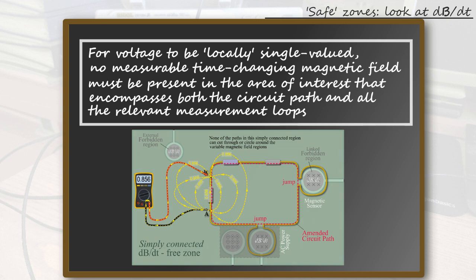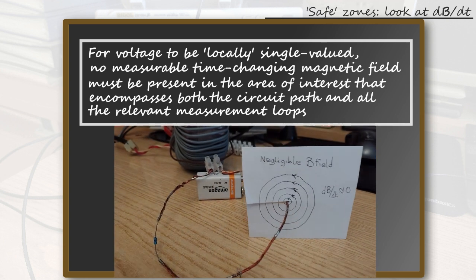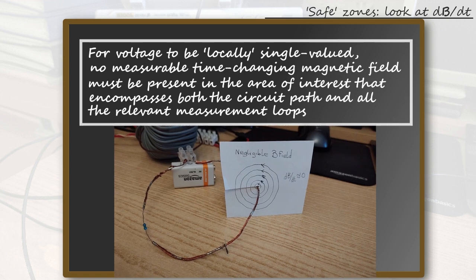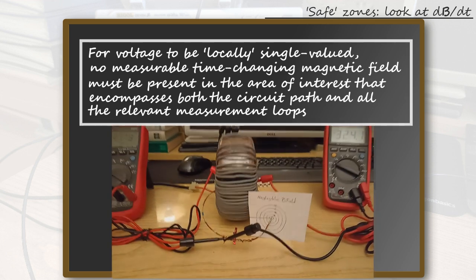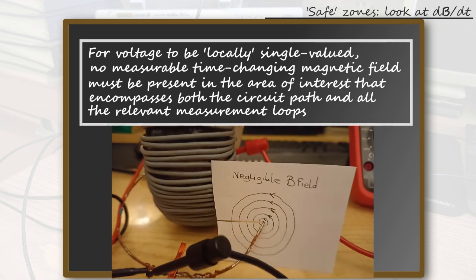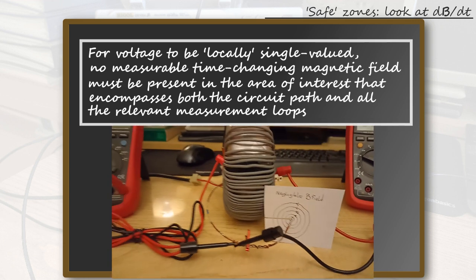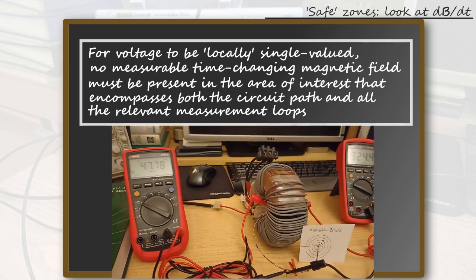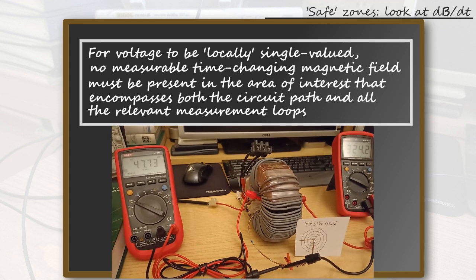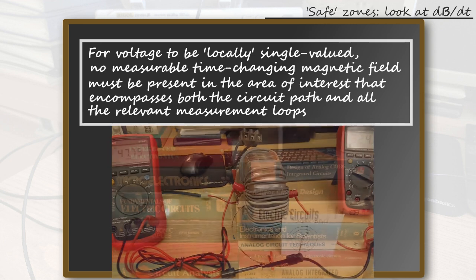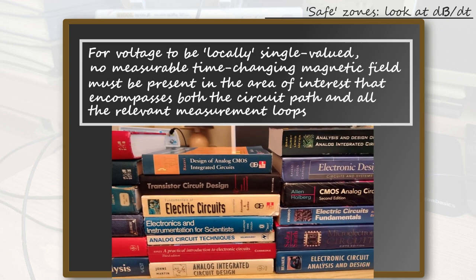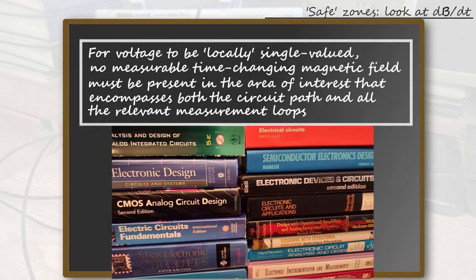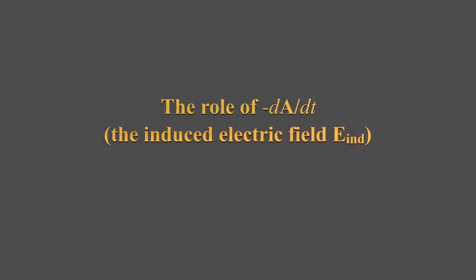Note that in all these circuits I am assuming there is no relevant magnetic induction associated with the current flowing in the circuit itself. In circuit theory terms, I am assuming that the self-inductance of the circuit itself is negligible. It is a very reasonable assumption, shared by a large swath of AC and pulse circuits with small enough currents and low enough frequency, that is, most of the circuits you might encounter in general-purpose electric circuits courses.